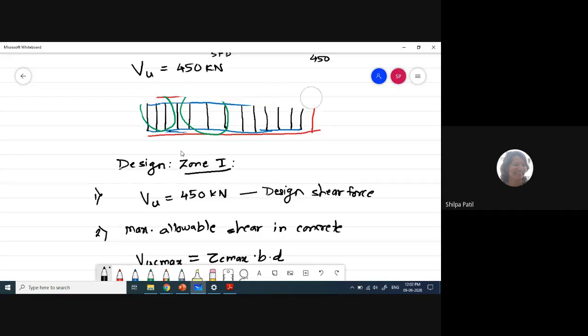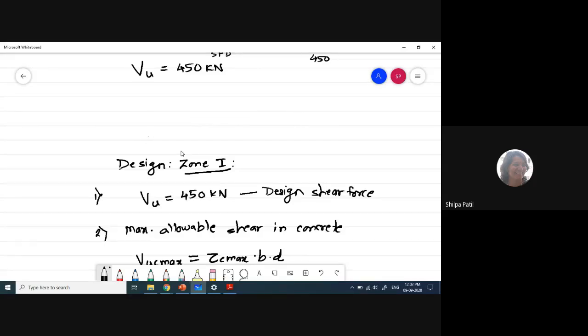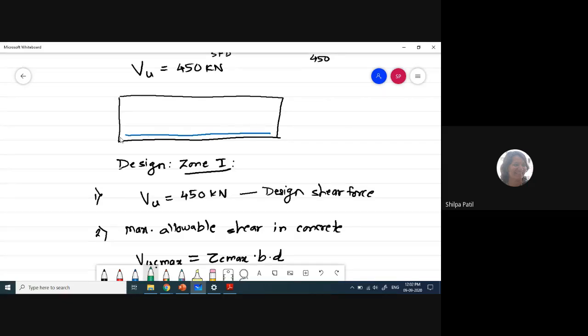this diagram, same diagram again here, to show you the bent up bars. In practice, in the beam and also in the slabs, alternate bars are bent. So if this is my beam, and this is the first bar, the second bar I will show by a green color, which will be exactly on the side of the blue bar.